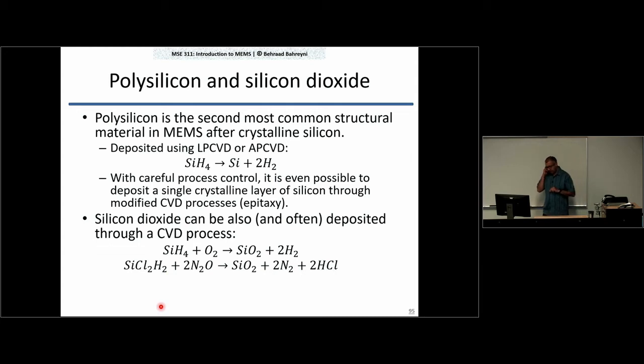Now, one problem that happens from time to time if you do not set the process parameters correctly is that you get some snowing effect. What that means is that your gases react above your substrate instead of on your substrate, right? So this is something that I maybe forgot to mention when I was talking about why I want the gas molecules to be adsorbed to the surface first. That's because I want to avoid snowing, right? So I don't want the reaction to happen above the substrate and the byproduct to fall onto the substrate. In that case, I will have very poor adhesion or no adhesion.